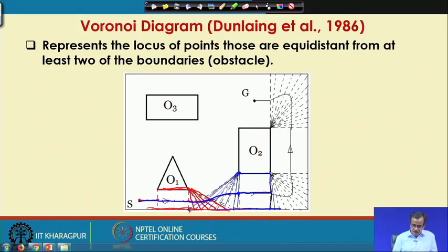So, we draw all such straight lines here, and for each of these straight lines we try to find out the midpoint. These are the midpoints. From here we can just join them by a smooth curve. So, the point robot has reached up to this. Next we consider this vertex and the boundary of the field. This is the straight line, and we consider the midpoint of this particular straight line.